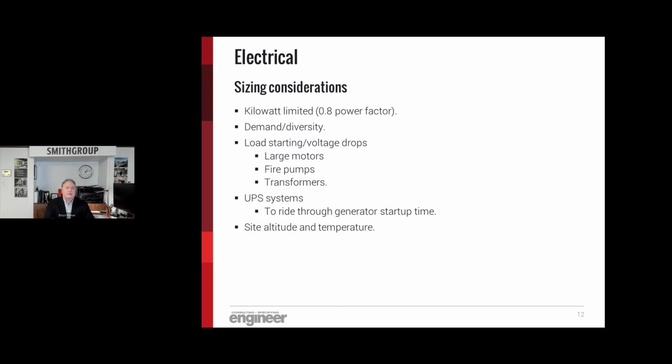So let's talk about some of the sizing considerations. One thing that as a young engineer was kind of a learning experience for me is you see generators rated in kW or kVA. You might see a 2000 kVA generator. As electrical engineers, we tend to focus on kVA as the total power. But it was interesting to learn when I was a young engineer that generators continue to have a 0.8 power factor rating.